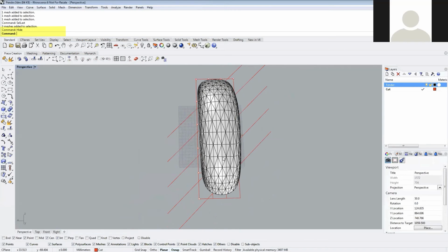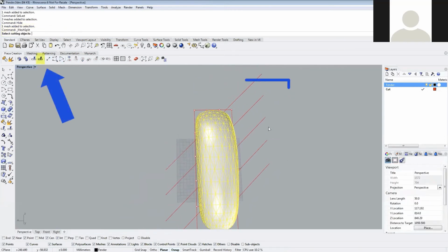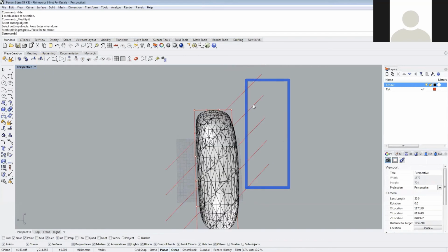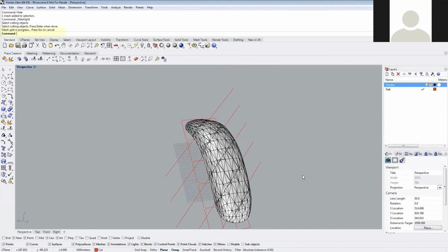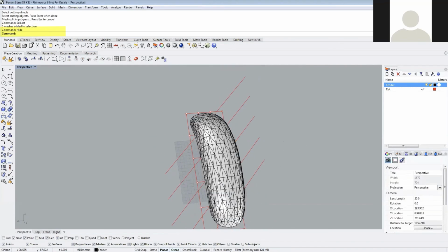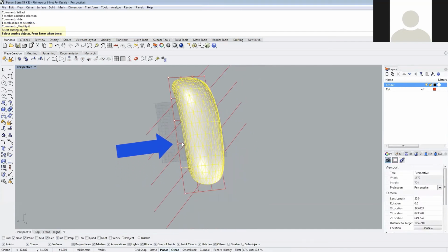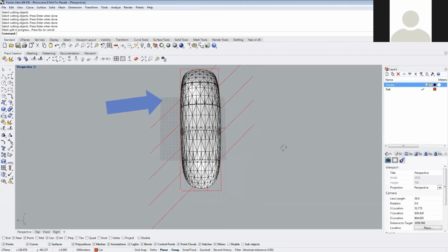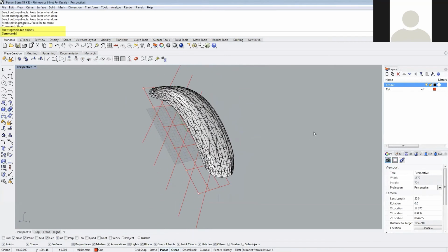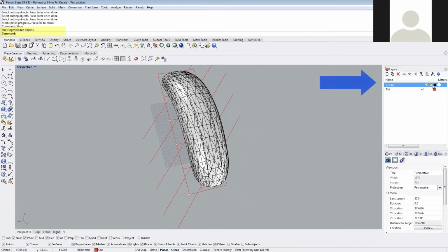This is going to expose the middle layer. We're going to again use our mesh split command. We'll select our bias curves, and we'll split those all along 45. SelLast to select the split meshes, and then we can hide them. And lastly, we'll use the mesh split command, and we're going to split these horizontally. And we'll use the show command to bring back all our layers. So now we have all of our different layers. They've all been split up into plies.